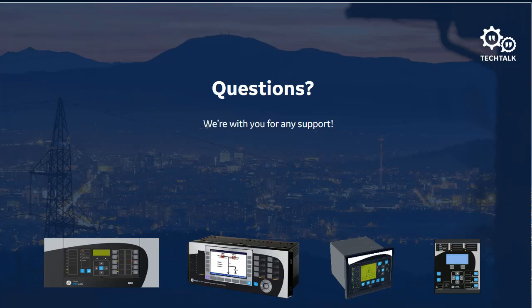The only negative or zero sequence current we should see in steady state non-fault conditions is the current associated with unbalanced loads, which if we've done our work right, we balance as much as we can, so that should be very small. Likewise, since our negative and zero sequence currents should be small, our negative and zero sequence voltages should be very small also. So we would never expect, in the steady state, those quantities to be anywhere near the positive sequence quantities.